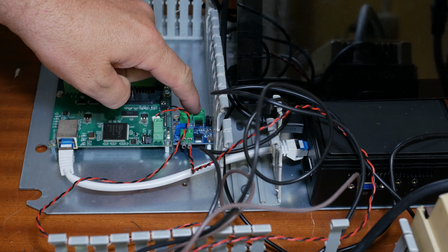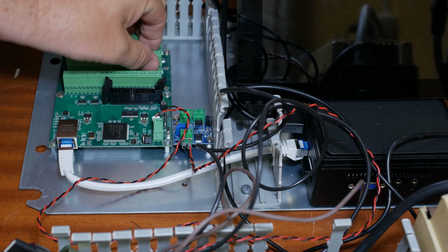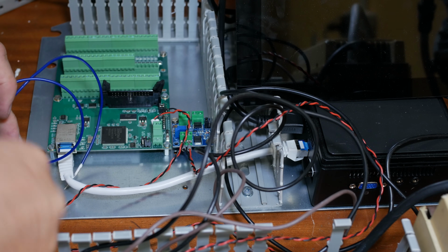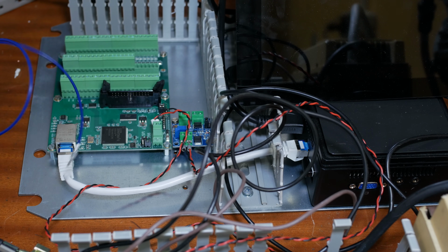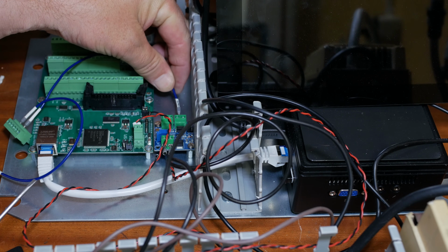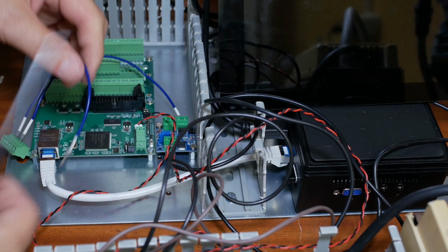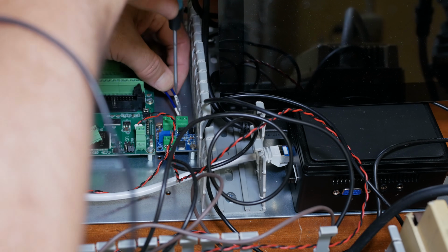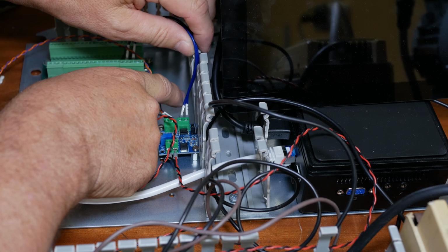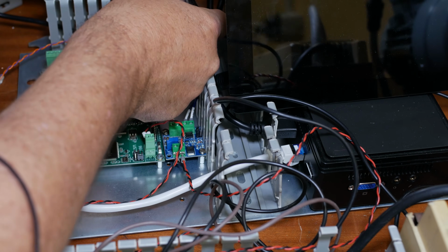Now that I've made up some cables, I can start connecting up the Mesa card to the pulse width modulation converter. Now on the Mesa card, this is terminal block number 2. Okay, and these go down to ground. And pulse width modulation input. So these wires should each go out into the cable canal. I probably should have done that before I connected them.